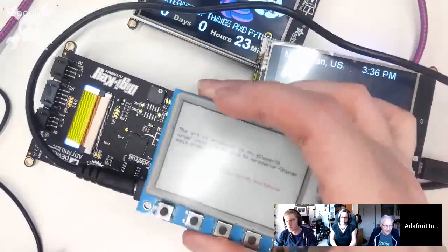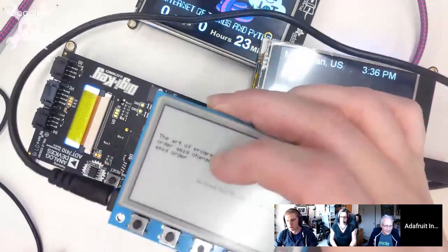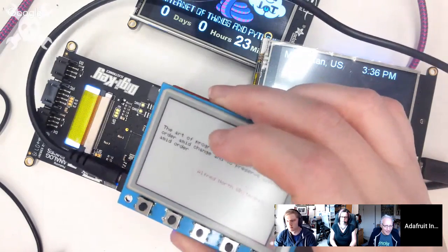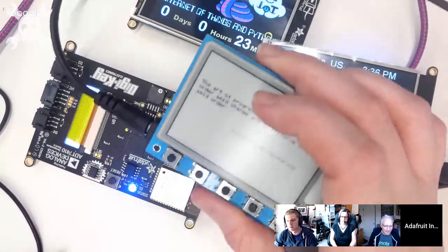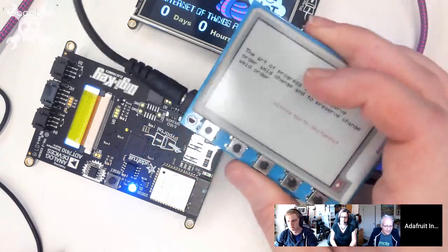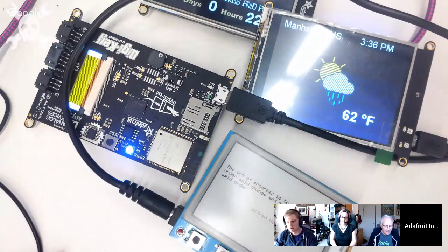This is how I test hardware. I have two things, and this was running for 3 days straight, so it seemed pretty solid. It's another nice thing about having the ESP32 as a coprocessor. If anything hangs or you get a memory leak, you can just hard reset it with a toggle and start over. Exceptions are great. There's exceptions and timeouts.